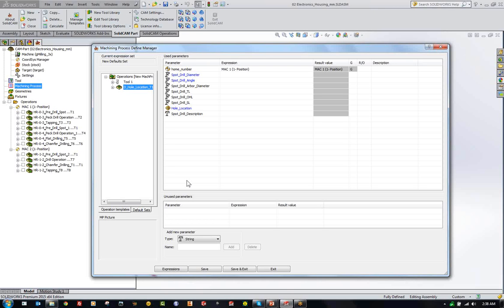And I think Ken is going to show you exactly how we can use this to our advantage. Right, so let me show them how that works. What we're going to do, because we have to test for that condition, I need to create a user variable. And the exercise here is to open your minds up to how to work with this. We are limited by what SolidWorks gives us, and we have to deal with that in that environment. So I'm going to create a float diameter.